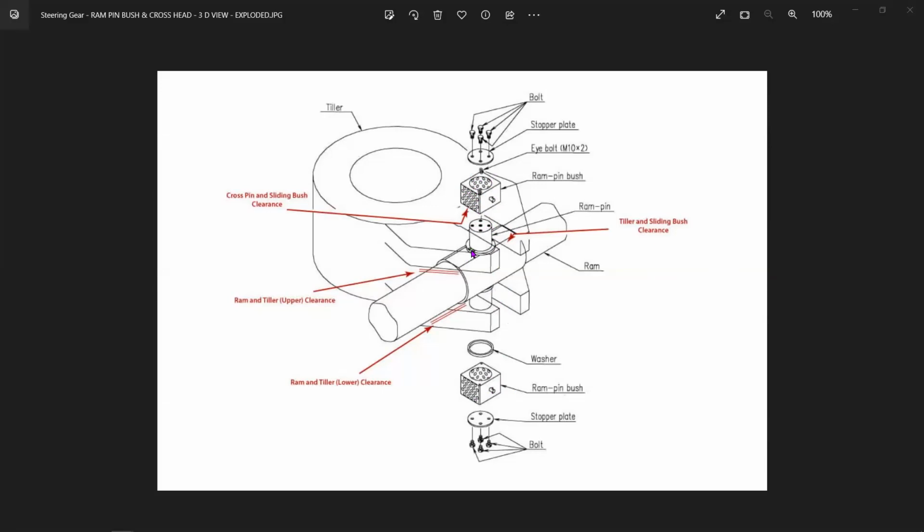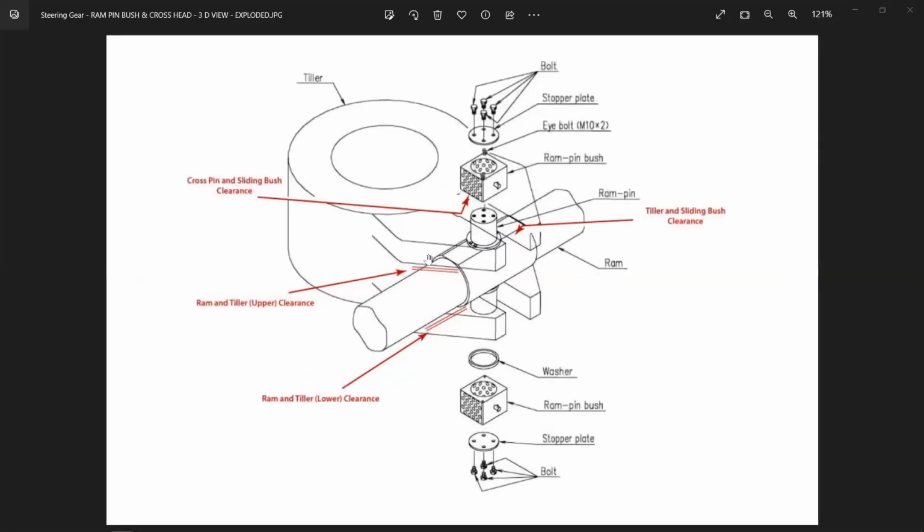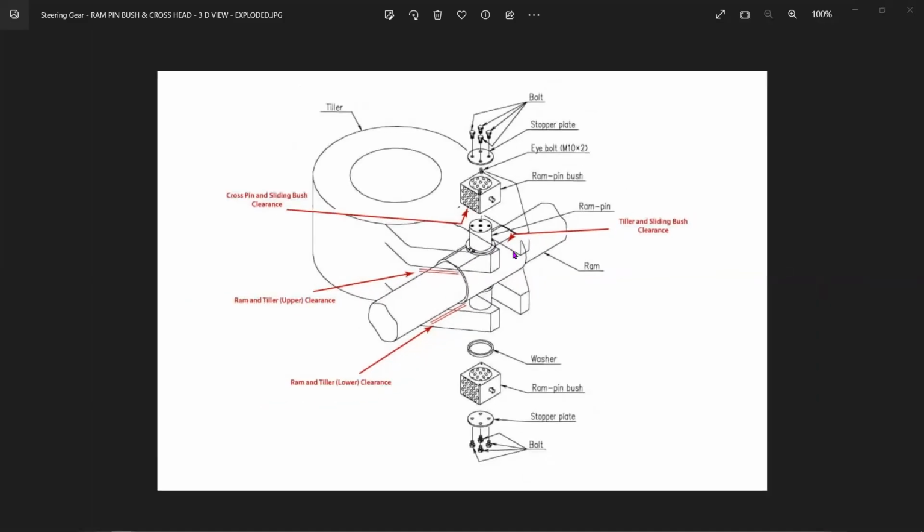So you understand the ram is now much more resilient, because the ram pin is a very small diameter compared with the entire diameter of the ram. So the idea is the entire diameter of the ram can be reduced. Earlier you had to have much bigger rams because you didn't have a uniform cross section. Here it is more or less a uniform cross section, but they've made a hole in the entire ram. What they've done is put an additional sleeve, which you see here, on top of this to give more rigidity. So the sleeve is put in.